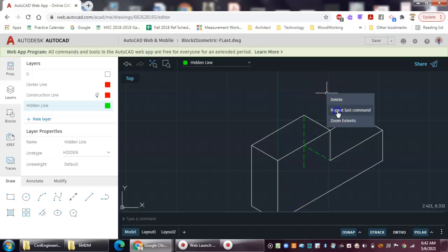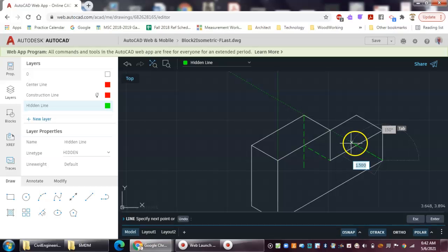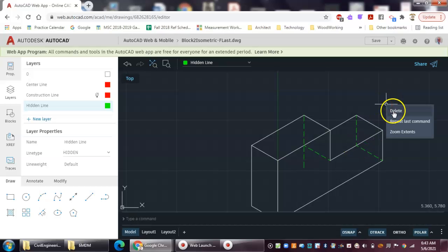And again, remember, we know what the actual dimension on this should be. So at 150 degrees, that should be 1.5 inches. And you see it just happens to kind of line up. And again, this is the math involved with the isometric drawing. The reason why it kind of falls on the line is that, with the way we've turned it, this object line here is directly over the hidden line that's the opposite corner of it.